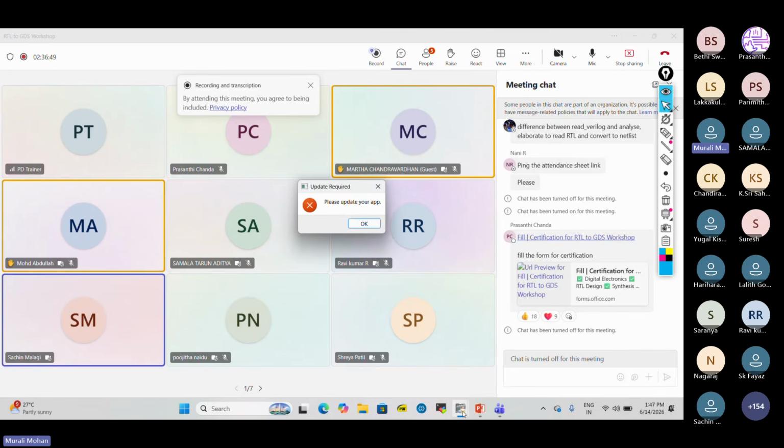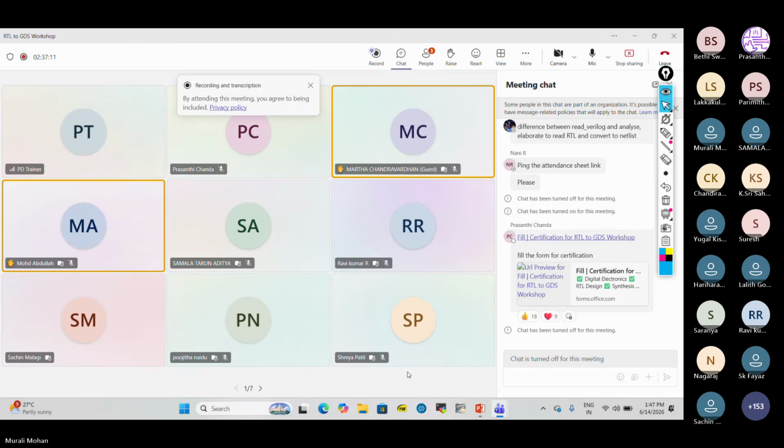Actually, we have the M9 plus MRDL metal layer, but in the subblocks and everywhere else we use up to M9 only, not MRDL. We ignore that metal layer because top level integration happens with the help of it, using a feed through technique. That means from the top block to the down block, any connection won't interrupt any other connection in between them. So for block to block connection, we need to use this MRDL layer, yes, at the top level.